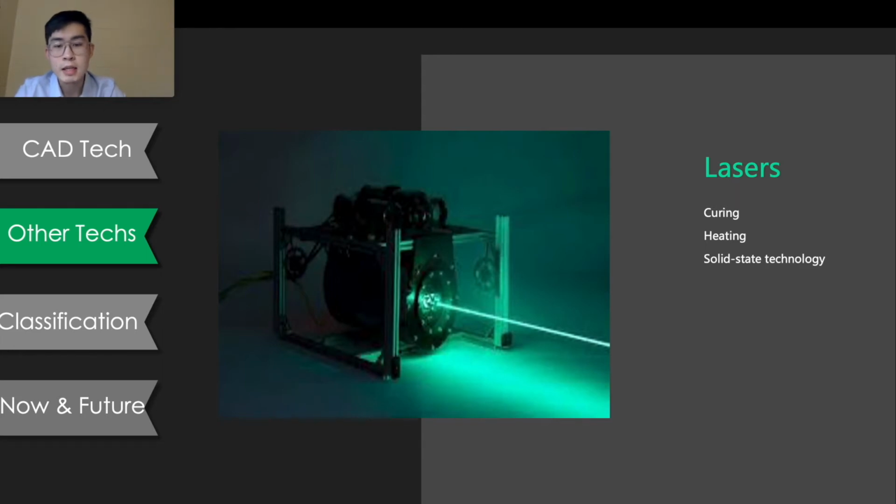For heating, the requirement is for the laser to carry sufficient thermal energy to cut through a layer of solid material, to cause powder to melt, or to cause sheets of metal to fuse. Earlier AM machines used tube lasers to provide the required energy, but many manufacturers have more recently switched to solid-state technology, which provides greater efficiency, lifetime, and reliability.